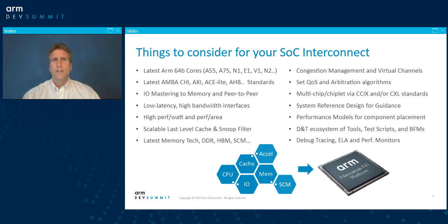Well, you and your customer may be trying to determine whether to build or buy an interconnect and probably have some performance, power, area, and cost goals in mind. And the SoC will have to handle some kind of I/O workload, software tasks executing on multiple CPUs, possibly a mix of accelerators and neural network processors. And you'll want an interconnect that can support different memories, CPUs, I/O types, maybe last layer cache, and maybe multi-chip.